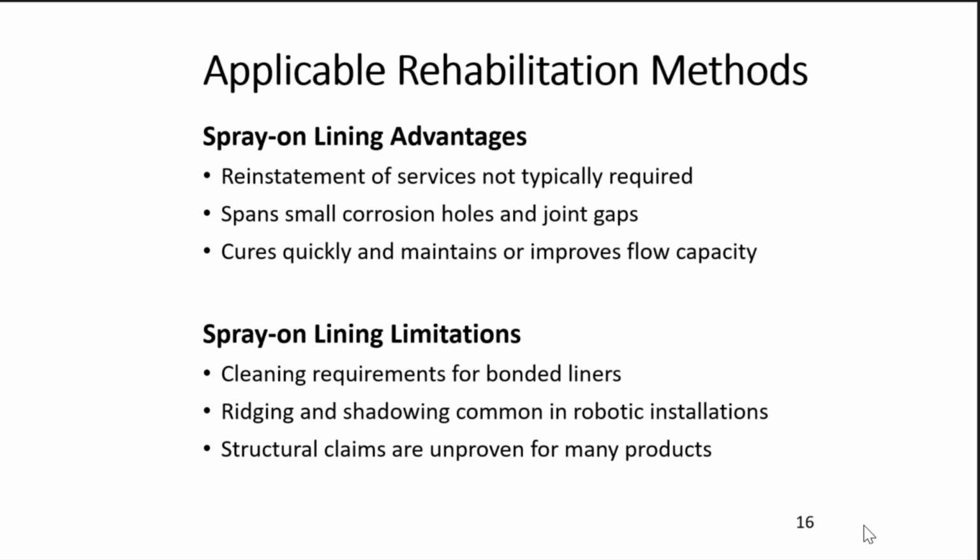So there's no excavation. There's typically not even a mechanical or physical reinstatement that needs to take place. Currently, they're mostly only used to span holes and gaps and not really a fully structural solution, although there's some recent developments there. And with some of the new blends like the polyureas, they cure really quickly. In fact, they set in seconds. You wouldn't turn the water back on in seconds, but they set really, really quickly. And so that's a big benefit to some of the old coatings that took several hours or sometimes days to fully get hard.